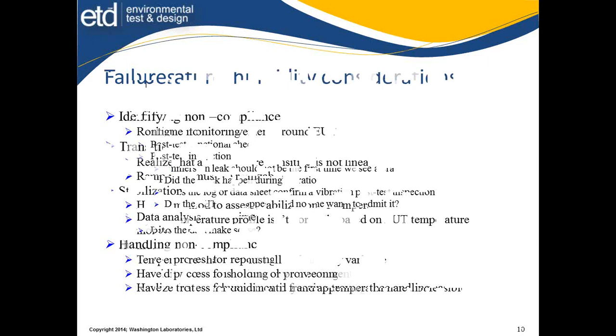These ramp rates also need to be realizable. This may call for 10 degrees C per minute. It takes quite a bit of chamber boosting to cool things at that rate, especially if you've got a high temperature mass that you're having to change. We can change the air in the chamber, but getting the chamber to stabilize there is not necessarily so quick.